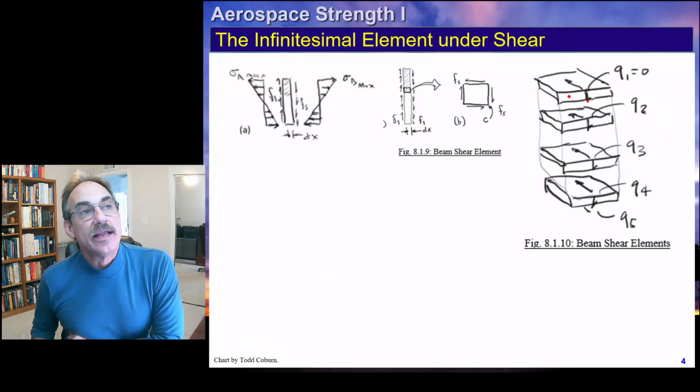Our stress here is, if we take the Q of this area times its Y minus Y bar to the neutral axis, that dimension, that gives us the Q to put into our VQ over I equation. If we come down 1 more inch, you'll notice we have the same area again, but now the distance to the centroid of that little piece is smaller. Now remember, what we're going to be getting is a parabolic distribution.